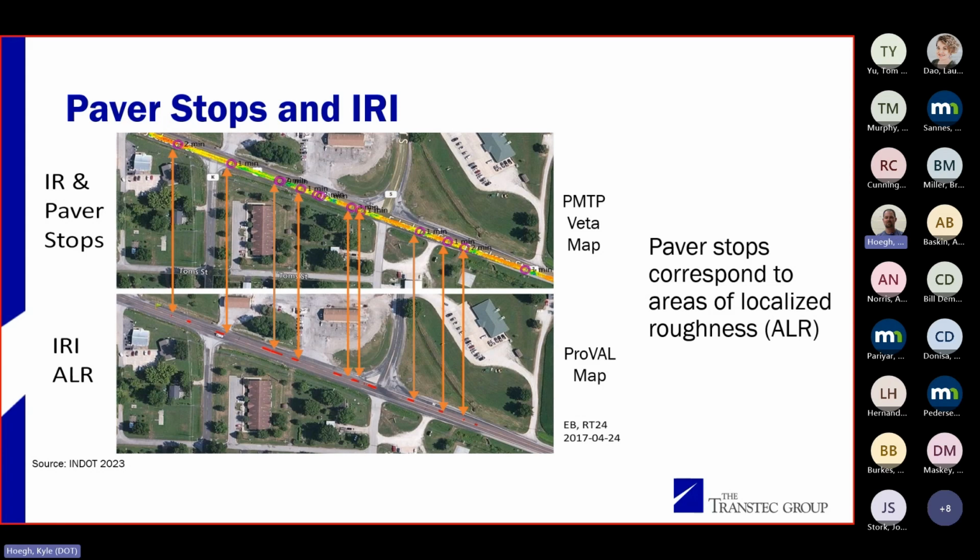I'm sure everyone's heard the water ski analogy, right? But if you are water skiing, do you want to stop frequently? No. Do you want to speed up and slow down frequently? No, not really. You want your guy on the boat to go nice and consistent. And the paver screed is set up very similarly. So consistent, nice, steady movement is what we're looking for.